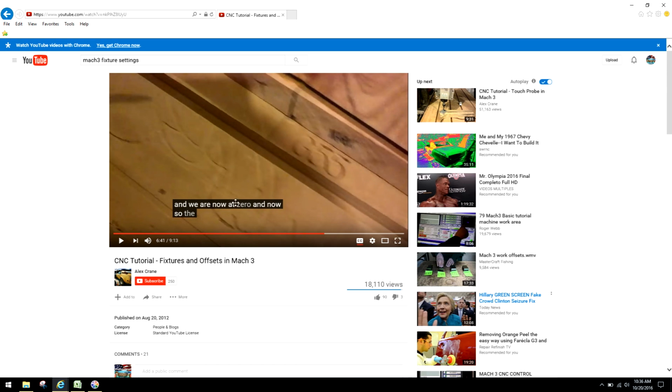Once again, take note also on the fact that he hit go to Z, and the machine automatically went over there, which is the exact location where he will be machining, which in my terminology I consider to be the true machine home, because that's where I will be machining all of my componentry from. Now, if there are some guys that want to argue that point and say, well, no, that's not your machine home, well, it's all based, again, on an arbitrary number. Do I care if my spindle is over here where the actual raw material isn't? On some applications you may care, but you could also set up another fixture to put you on the corner of that table where he considered it to be the absolute 0. Think about it in those terms, because it makes a lot of sense.